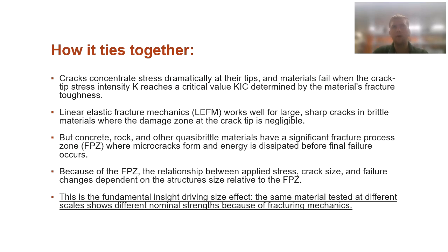So when you encounter a quasi-brittle material with that larger fracture process zone, that's when you notice this important transition between strength criterion and linear elastic fracture mechanics. And that's why we have this noticeable size effect in quasi-brittle materials, because of this larger fracture process zone where stresses are redistributing throughout the material and not concentrating at the crack tip like they would in LEFM.